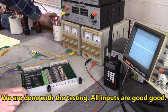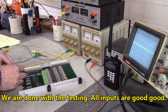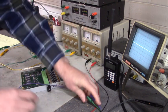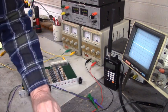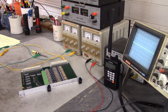That's it. Everything is good. And the only bad thing we found in that circuit was the D optocoupler input had failed. It had opened up.